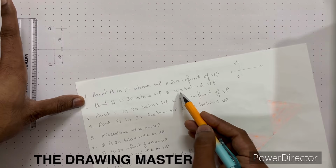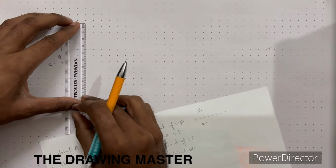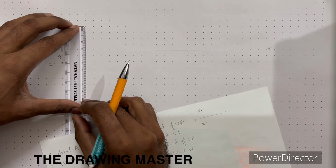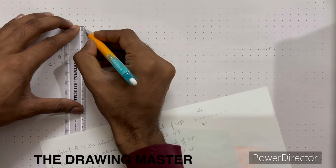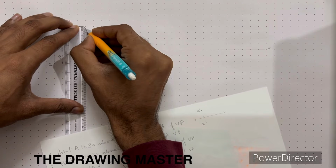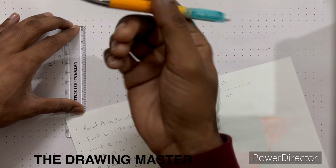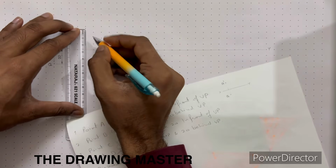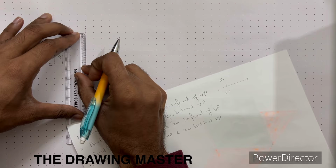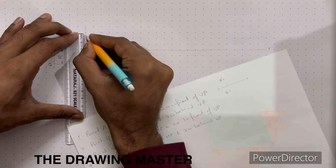Point B is 30 above HP and 20 behind VP. So 50% of the problem is the same. Above HP means above the reference line. This is the front view. And 20 behind. Behind means it will come upside. So on the same projection line, after the rotation of HP, the top view will come upside.